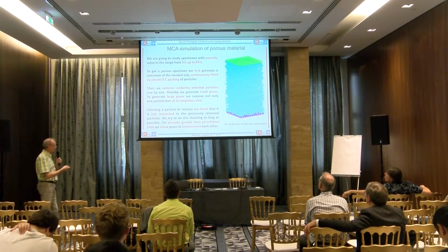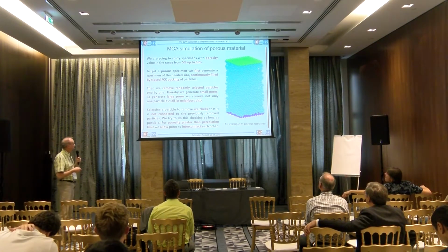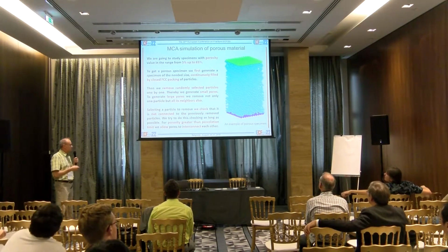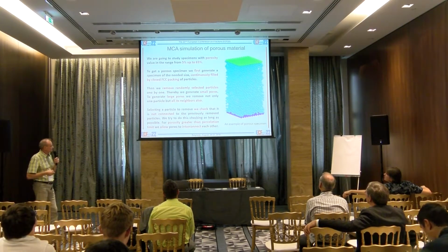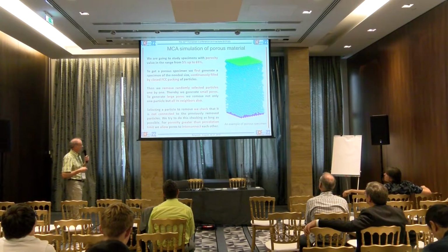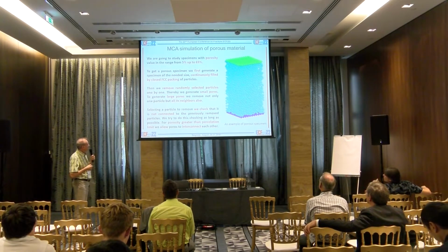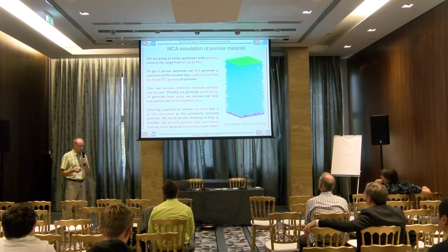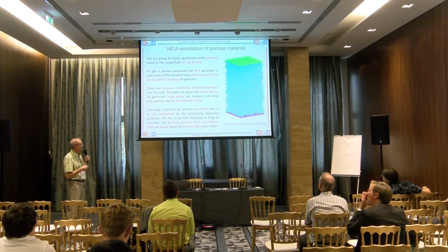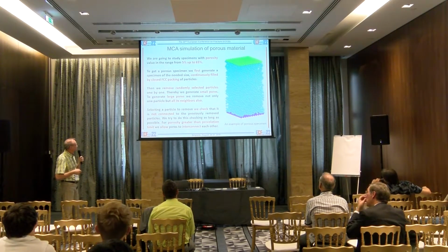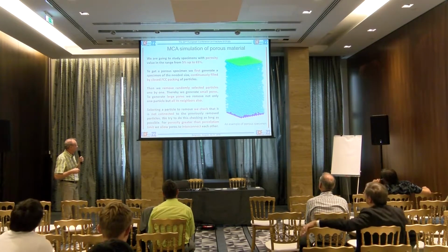And a little bit in detail. So we start with, let's say, the usual bulk material, which is a closed package of these particles, usually in FCC packing, and to get pores, we just remove some particles, so we have randomly selected pores, and we also check whether these pores are interconnected or not.